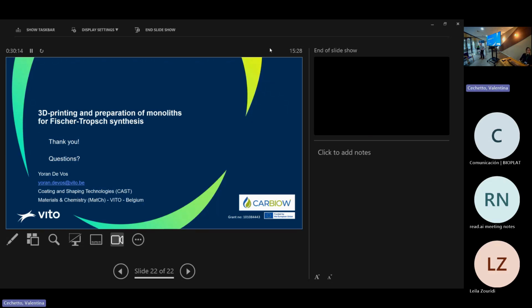Have you ever applied this technique to the production of conductive materials? Yes, we have printed titania, copper, iron, stainless steel. Metal printing can also be done, but of course the calcination and especially the sintering is then very important. For copper, we sinter under hydrogen atmosphere, for example. But we have some samples there.